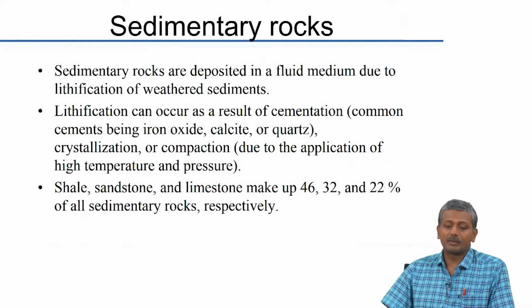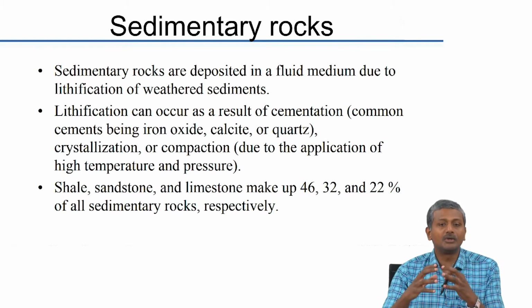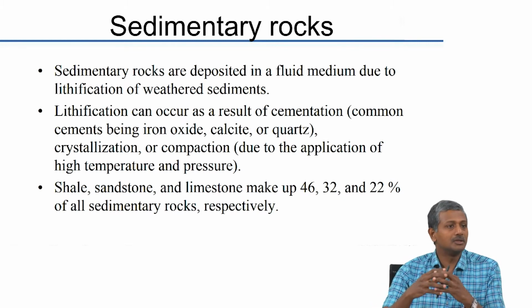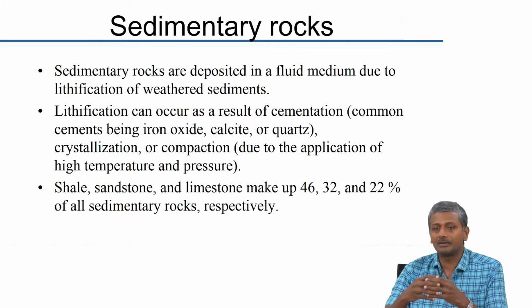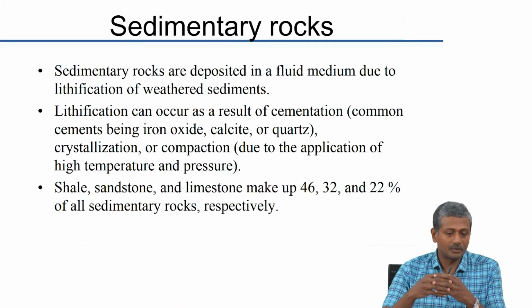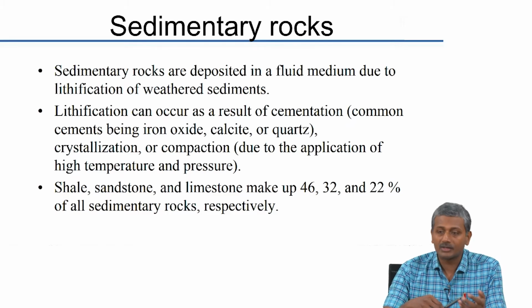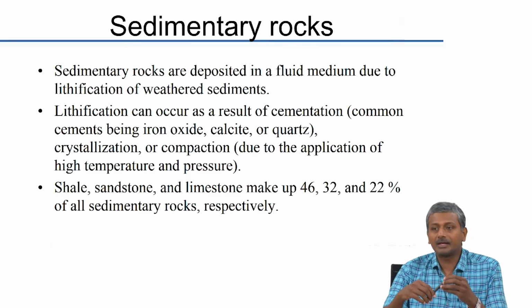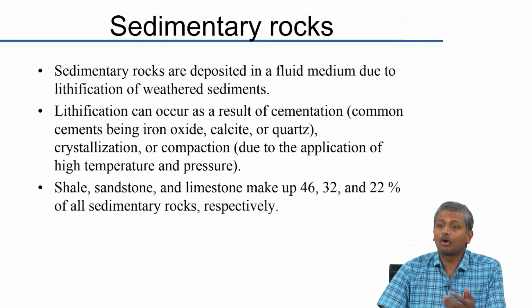Sedimentary rocks of course are deposited in a fluid medium due to lithification of weathered sediments. So, any sediment that gets weathered and gets compounded together either by the action of pressure or by the action of additional cementing materials like iron oxide or calcium carbonate can form a sedimentary rock. Okay. So, lithification can occur because of cementation, common cements being iron oxide, quartz and calcite, and the other reasons could be crystallization, like deposition of the crystals in one location, or compaction because of high temperature and pressure.